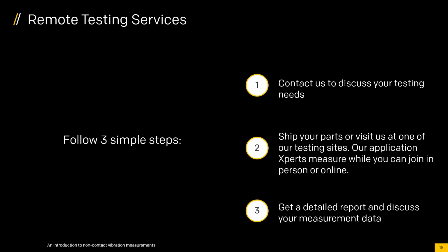Frequency doesn't change. If there's something at 500 hertz, you're still going to see it at 500 hertz. So if there's some sensor exciting your structure, that's the only thing. It depends what you are after. If you are after frequency, then it doesn't matter. If you're after pure, let's say, attenuation, depending on certain treatments, then you may absolutely want to compensate.